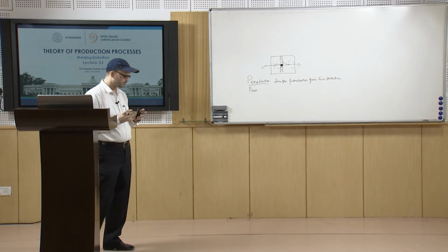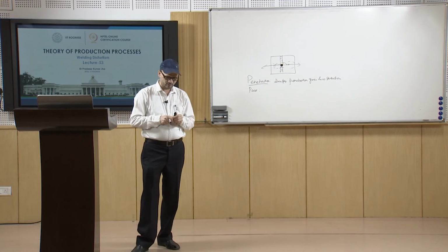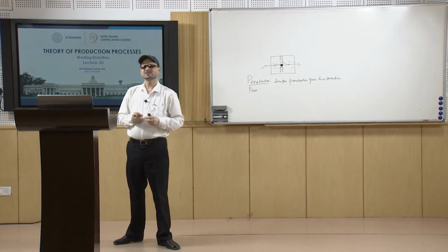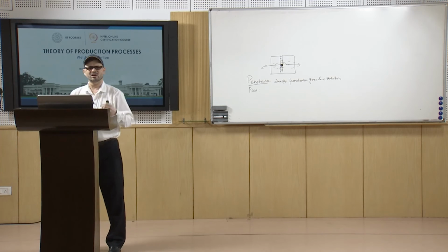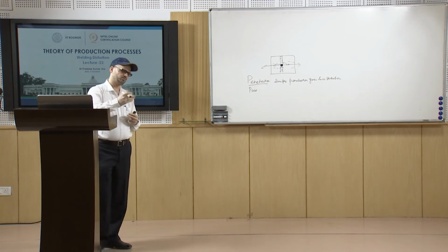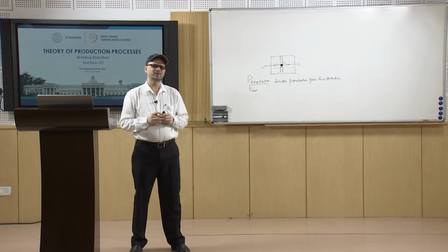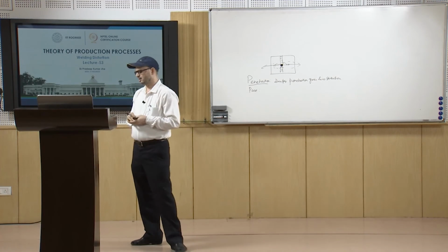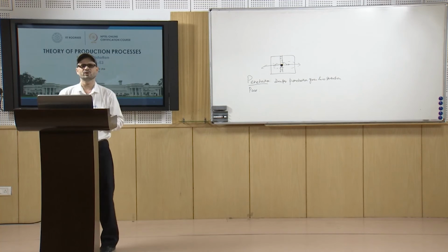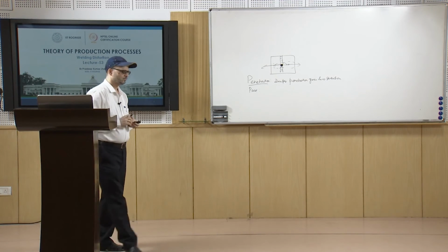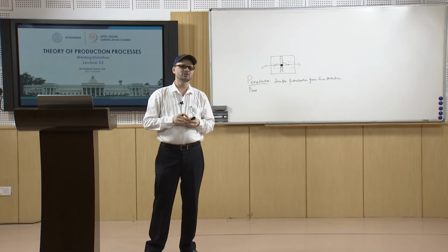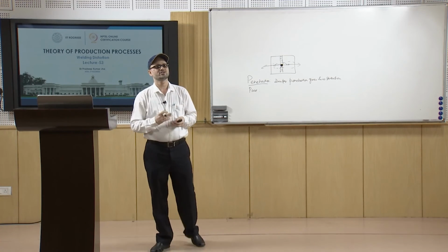So, in the case of welding of thin sheets, if you recall, when we used DC welding, with reverse polarity the work is negative, and with straight polarity the work is positive.